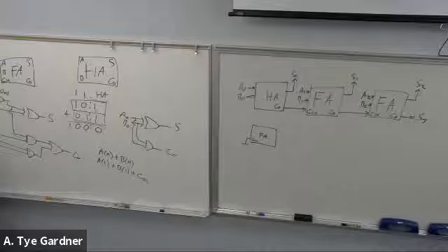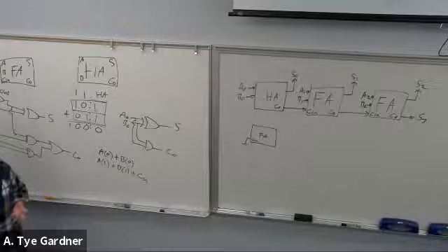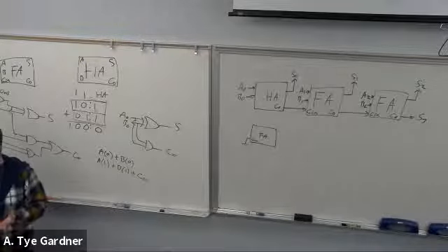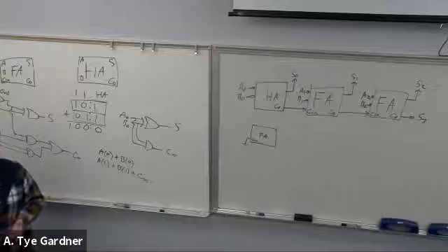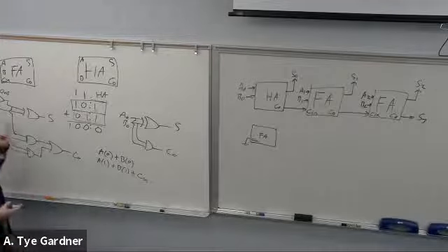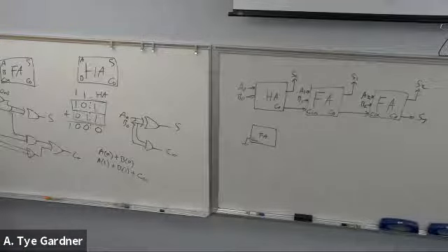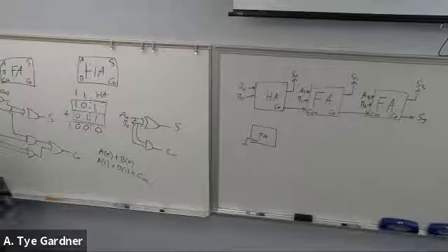The reason being that each of these transistors that you build a circuit on have capacitance. And capacitance is kind of like weight. It's how hard is it to move that voltage. And so when I have lots of transistors, it's slower to move. And when I have fewer transistors, it's faster to move. It's easier, right? So like if I want to pick up this book, I can just pick it up and throw it across the room. But if I want to pick up and move the table across the room, I would need some help, right?